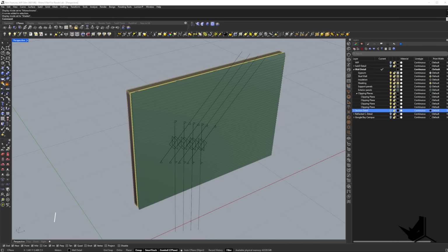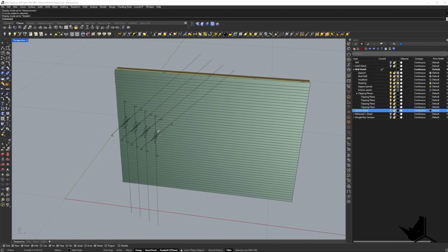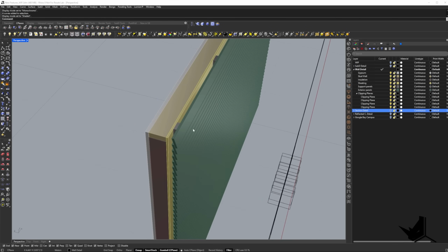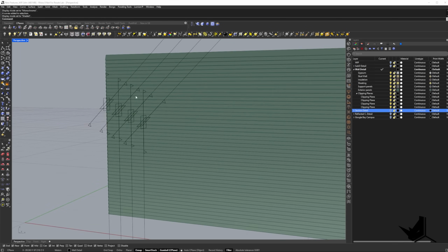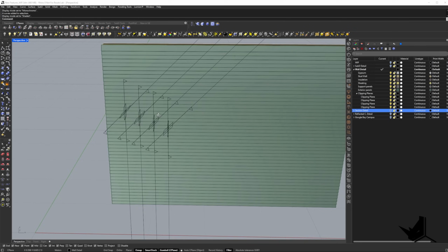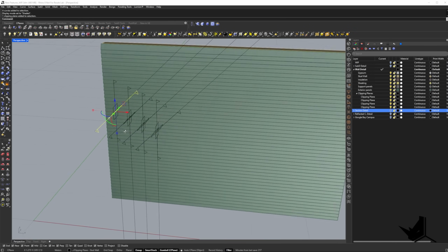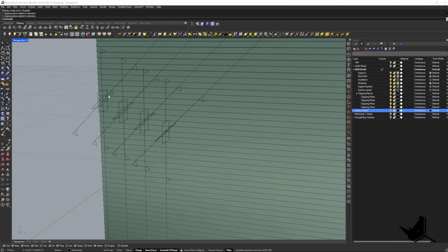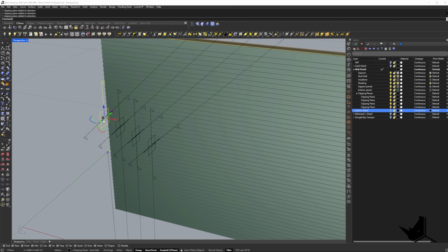This is again in my top 3 features, and it's called selective clipping. Selective clipping allows us to create multiple sections within the same detail. And in this case, you will see what this means. So for example, here you can see I have a wall that has different layers, and you can see here that we have a couple of different section planes. We have the planes that are located like this, and then we have the ones which are created by an angle, and both of these have the same properties.